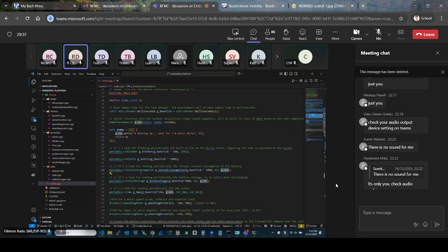So in this manner, it is able to communicate with the Raspberry Pi via serial. Then we have the total voltage component. This component is called every 3 seconds, is reading the data from the A4 pin, analog pin number 4, and is sending the data via serial to the Raspberry.